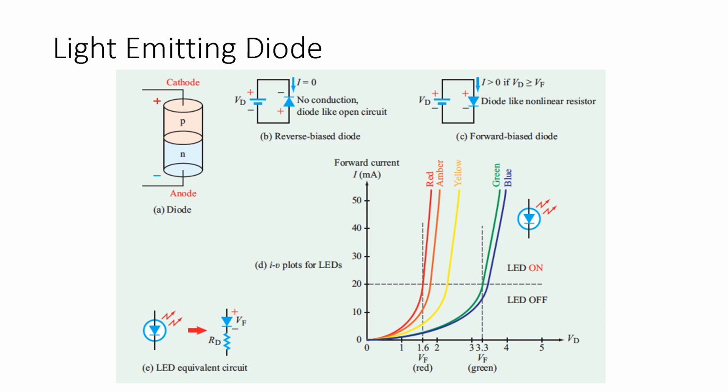A forward bias diode, however, is if you put the LED in what I think of as the correct direction. This is going to make light as long as VD is greater than VF, which means that the power supply has a voltage that is greater than the forward voltage, or the voltage to turn that LED on. So mathematically, if the LED requires 3 volts and you put only a 2-volt battery in front of it, that LED isn't going to turn on at all.